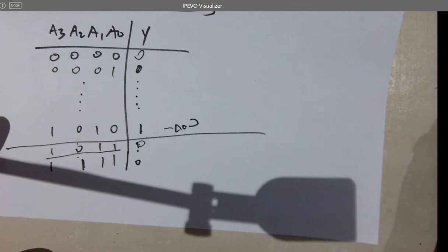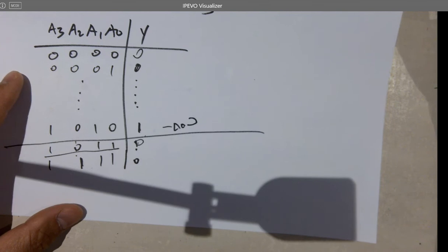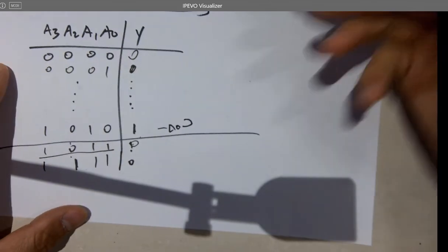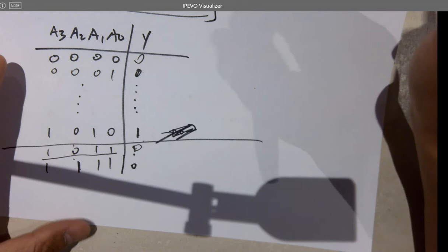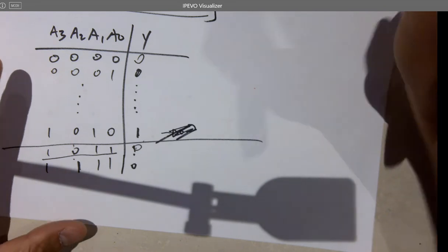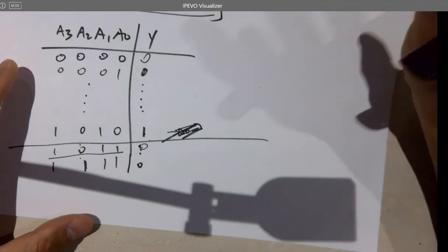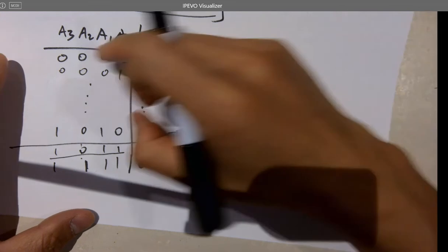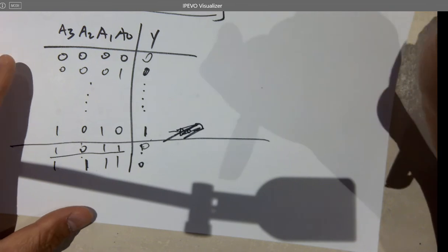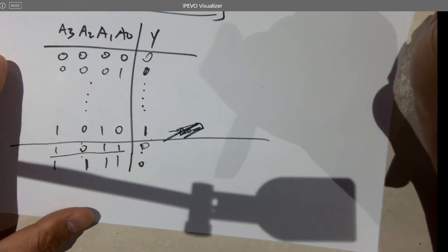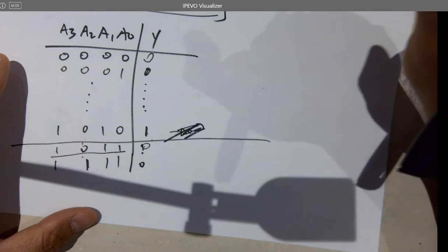By what? Yeah, so what's the next step though to get the gates? In digital computer logic design in 241, the online class you took, after you get a truth table, what's the next step usually? If you have not too many bits, like 3 or 4 as a maximum, probably 2, 3. Is that the K map? So you can simplify it, and then get all the logic expressions for the output.